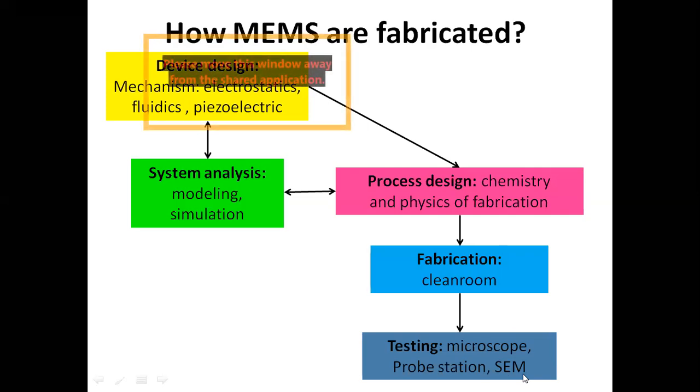And afterward, there will be the characterization. In it, you have to apply certain voltages or currents to the device, and you have to measure the displacement, velocity, or sensitivity, etc. So this is actually how you go through the fabrication of a microfabricated device or MEMS device.